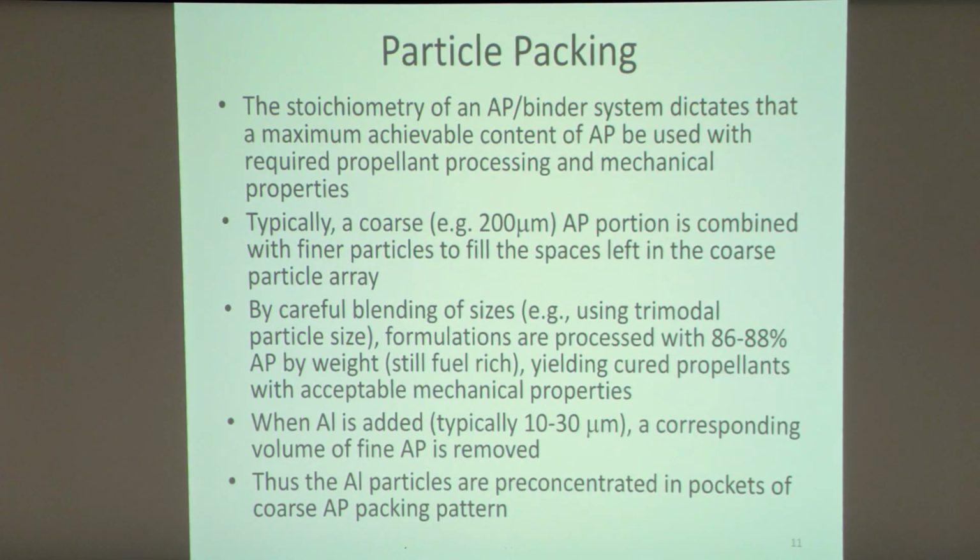Plus the mechanical characteristics, behavior will be poor at the very end of the mixing. So typically a coarse 200 micron AP portion is combined with the finer particles to fill the spaces left in the coarse particle array. By careful blending of the sizes, for example, using a trimodal particle size, formulations are processed with 86 to 88% AP by weight loadings, which is still fuel rich, that yield cured propellants with acceptable